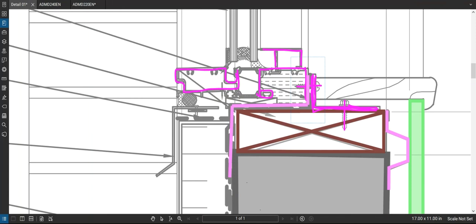And then that way, if there's any leaking through this window or door system, whatever it is, if any water gets down into here somewhere, there's a moisture membrane here that'll kick the water out, and it won't go back in that way because there's a dam there. So that's a good thing to have on every windowsill or door sill situation where possible.